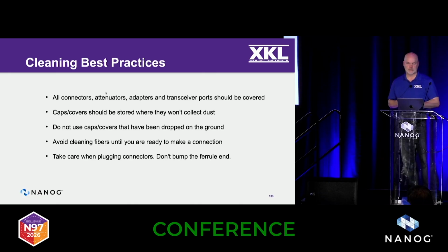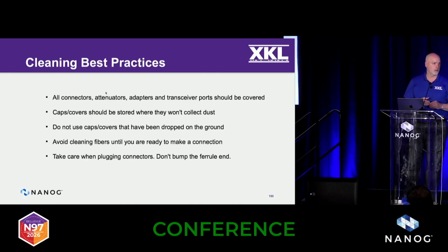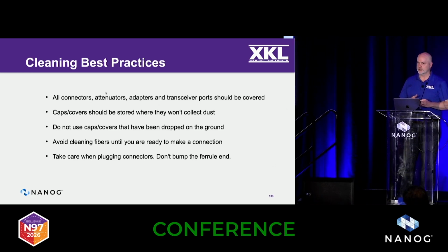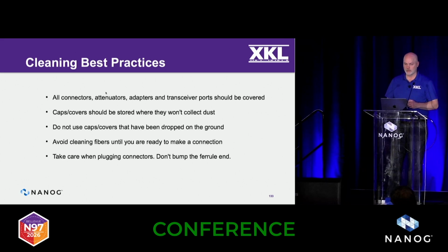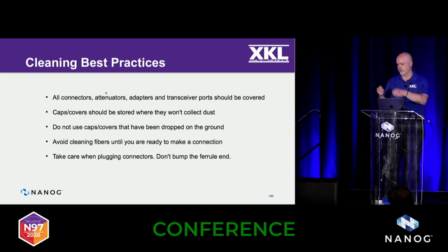Best practices. I probably harp on this too much, but I've just seen so many problems and so much time wasted for something as simple as good hygiene. So you got a connector in your hand, take the cap off, clean it, put it in. Don't take the cap off, put it down, go get the cleaner, come back, or clean it and then put it down and then come back. You got to follow a good sequence, and this will keep your fiber plant clean.